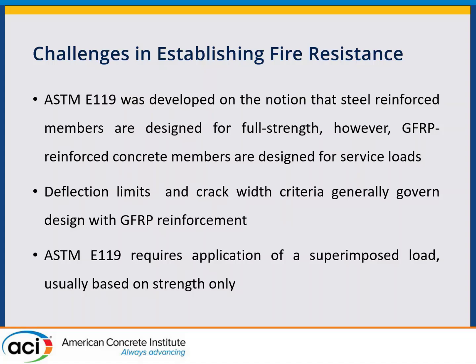When you design a structure for steel reinforced concrete or many other structures, the design is largely guided by strength. That's your governing parameter. So the tests are all geared to finding out how strong the member is, and then we figure out what load to apply to that member. But you can't do that with GFRP, because if you designed it for strength, nobody would walk on it because the deflections would be massive. You would have really wide cracks. Everybody would say this thing's going to be falling down.